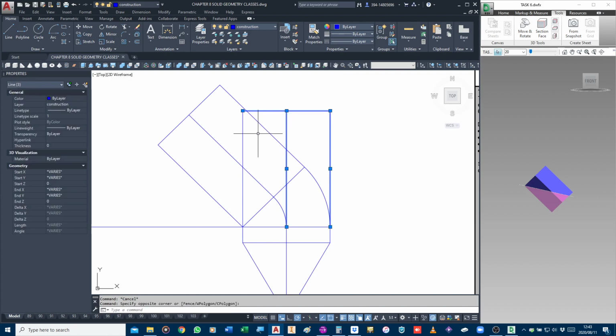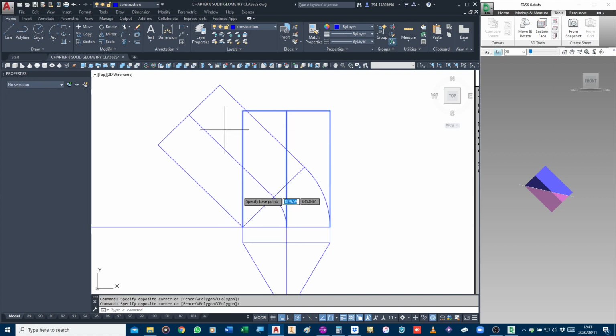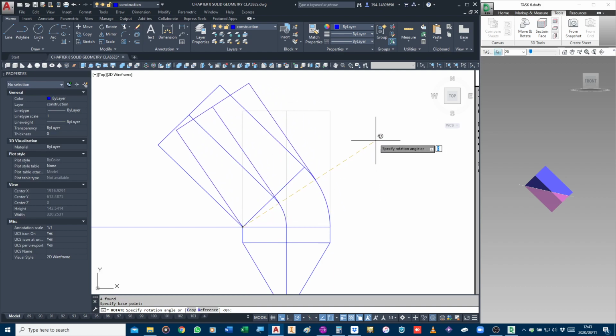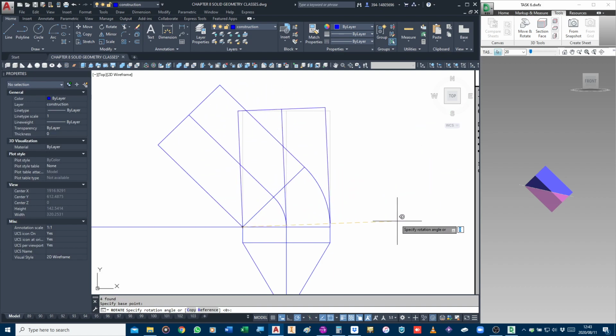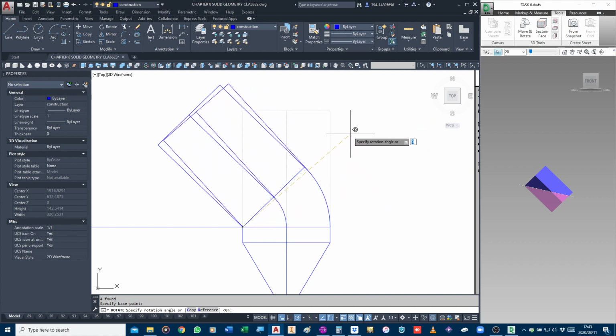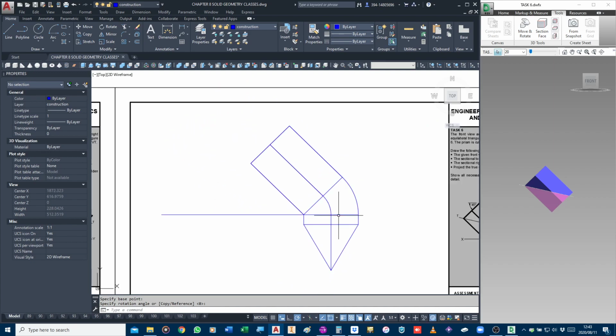So if I just take this quickly and show you, I now rotate on that one, and that's basically what we're doing. We're tilting it at 45 degrees. It was standing flat. It is now tilted at 45 degrees. So I can just leave that there. The next step, remember what I said when I started with the section. I said, do not put the section in immediately. The first thing that we want to do is find the top view of the tilted solid first.